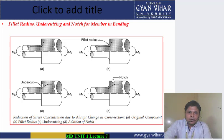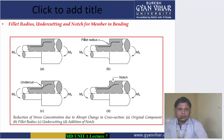So in such cases, the shoulder creates a change in cross section of the shaft, which results in stress concentration. As you can see in the diagram, a bar of circular cross section with a shoulder and subjected to bending moment is shown. Ball bearings, gears or pulleys are seated against these shoulders. There are three methods to reduce stress concentration at the base of these shoulders. These three methods are shown in the diagram also.